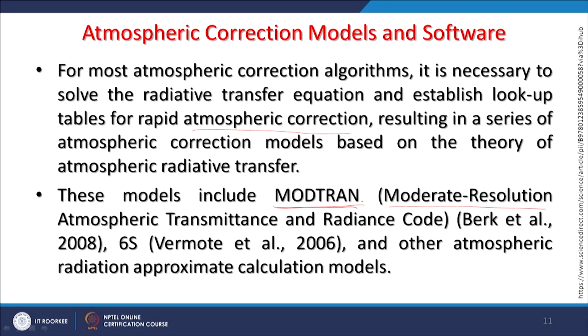But when we go for very high resolution images, the swath becomes very small, and therefore getting input data only for that part of the image becomes further difficult. When we go for coarse or moderate resolution images, then somewhere at least within that image I might be getting those atmospheric data. That is why fine resolution is another problem.